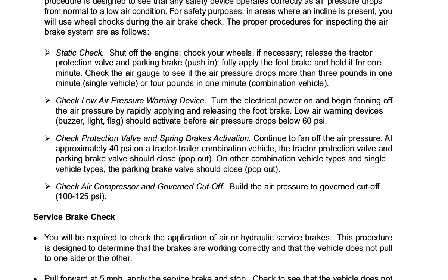Check protection valve and spring brakes activation. Continue to fan off the air pressure. At approximately 40 psi on a tractor-trailer combination vehicle, the tractor protection valve and parking brake valve should close, pop out. On other combination vehicle types and single vehicle types, the parking brake valve should close, pop out.